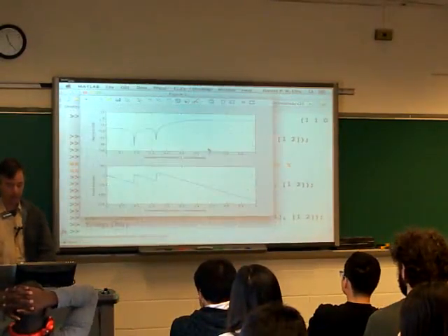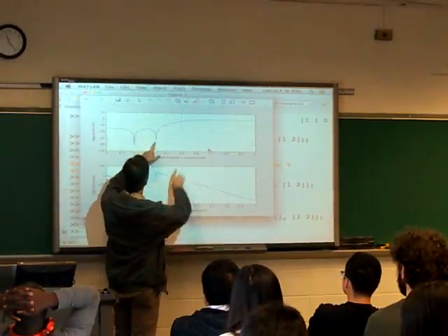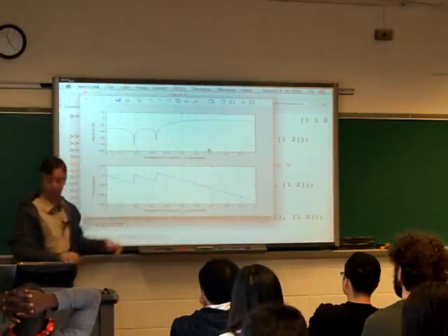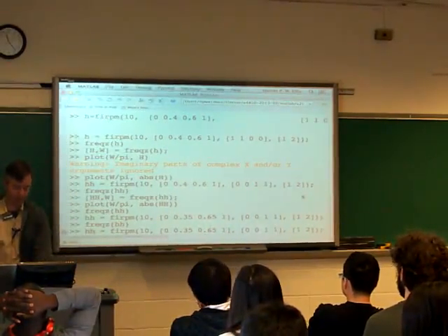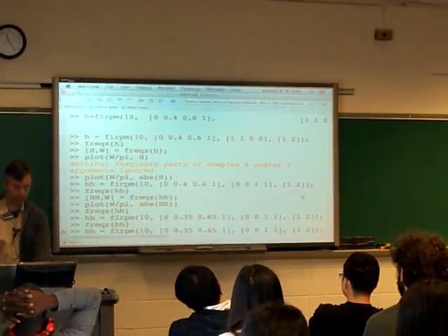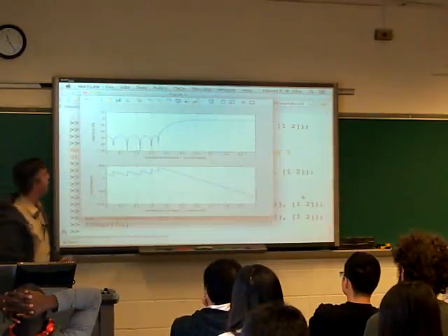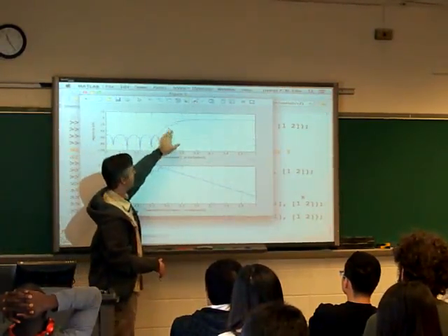And now this thing is a little broader, but now we've got minus 30 dB of rejection here. Or we could up the order, of course. That's the normal thing you'd do if you wanted a better filter. So if we make it 20, and look at that, now we've got our errors at minus 50 dB, and